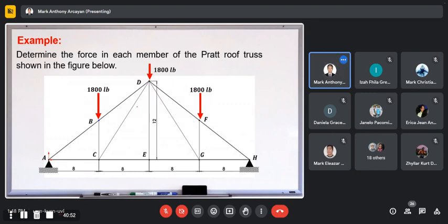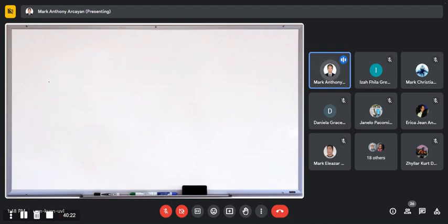But luckily, we only need 7, because our truss is symmetrical, as well as the external loads, right? 180 on the left, 180 on the right, then 180 in the middle. Then the design is symmetrical, as well as the supports, no? The supports are pinned. So it is symmetrical, and we can consider only half of the members in the analysis. Okay, so let's start our solution.